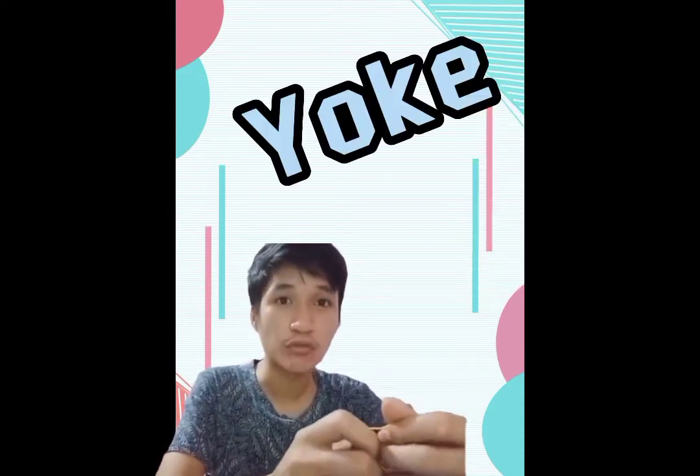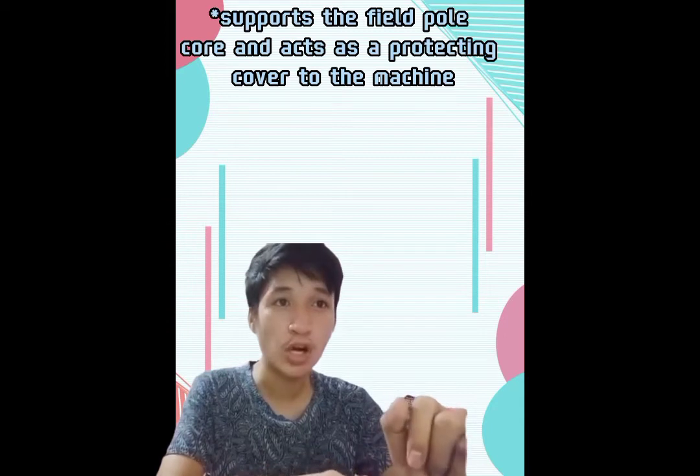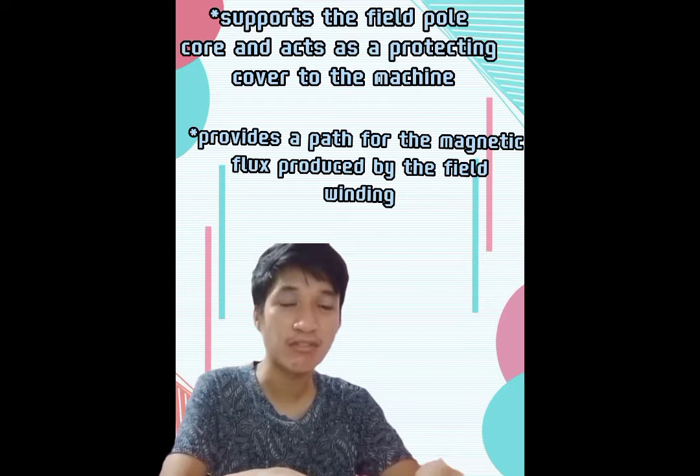Let's start first with the yoke, which is the outer frame of a DC generator. It is a hollow cylinder made up of cast steel or rolled steel. The yoke serves two purposes: to support the field pole core and act as a protective cover to the machine, and to provide a path for the magnetic flux produced by the field winding.